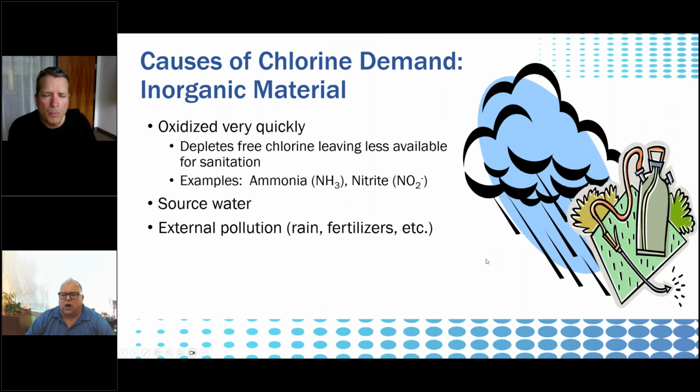But chlorine demand is very common. It's common in salt pools, it's common in traditional chlorine pools, it's common in every pool. And unfortunately, as a human race, we're not very kind to our environment. And the worse we are to our environment, the more things come into our pools from a lot of different sources. Pollution, rain, fertilizers, source water, all these things get into the water. And if chlorine will interact with them, then they will eat up chlorine. So the more things that chlorine has to interact with, the more chlorine it takes to be able to keep that residual where it's supposed to be.